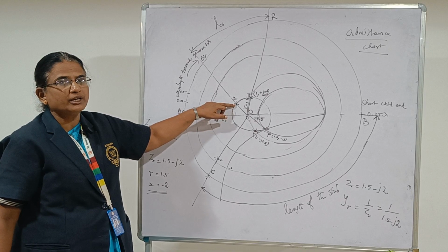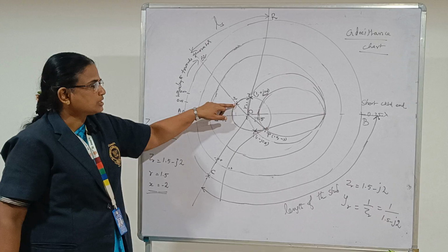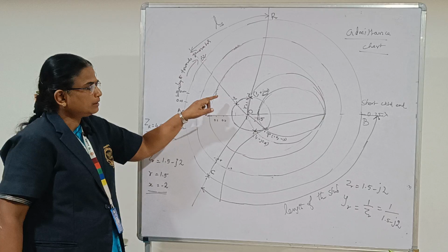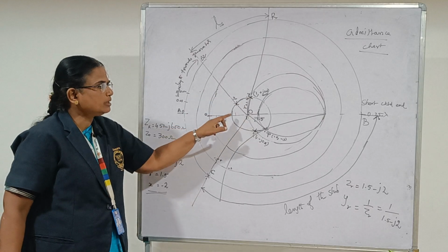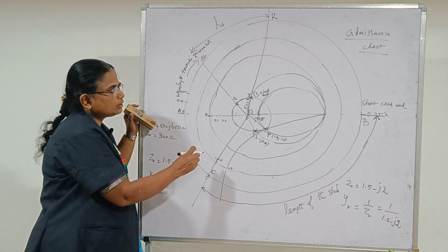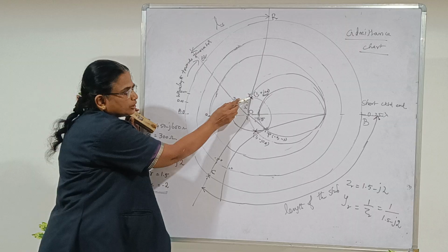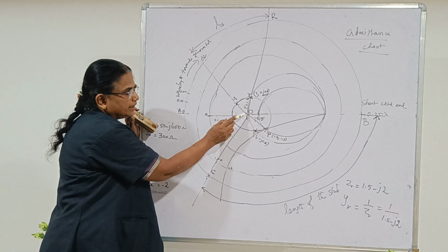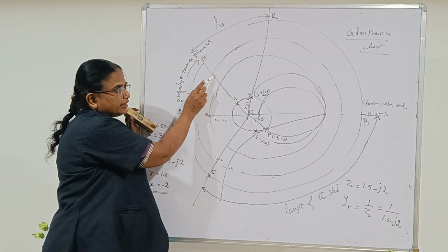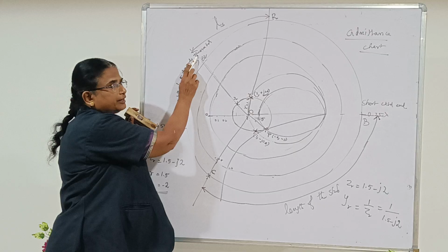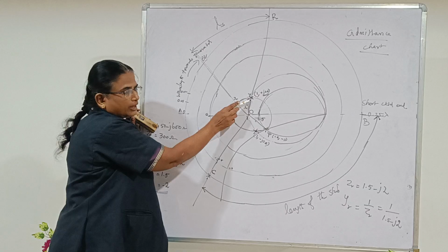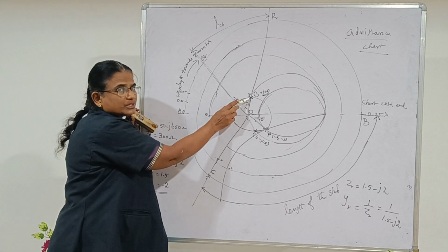So now we are going to make use of the chart as an admittance chart. And then you find the intersection of the drawn SWR circle and the R equal to one circle. So there are two intersecting points. Locate the two intersecting points, and then from the normalized load admittance, on this wavelength scale, you move in clockwise direction and locate the intersecting point which comes first.